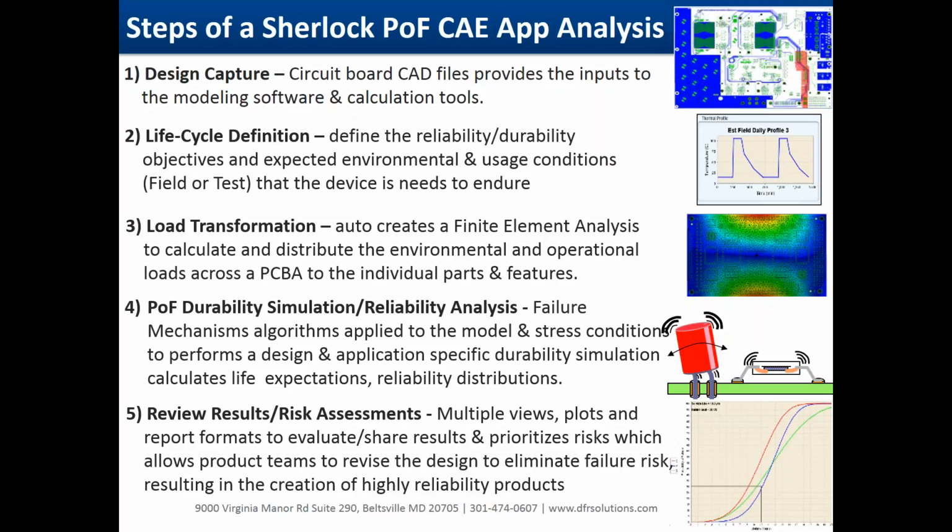Only instead of having to do a new design and build a new set of parts, which would take you a couple months, and then run another 16 to 20-week test to see if you were successful or not, you can interact and make changes in the virtual environment while it's still in the Sherlock tool, and then rerun it in another couple minutes and see if you fixed the problem or not. And the intent is that you keep doing virtual design optimization until you come up with a highly robust product.